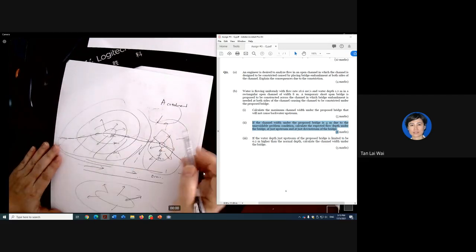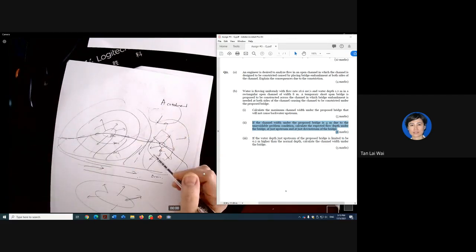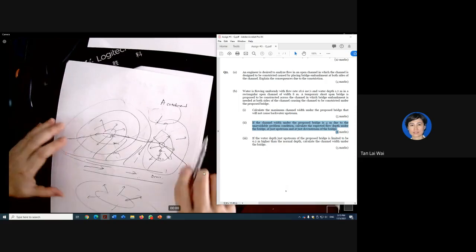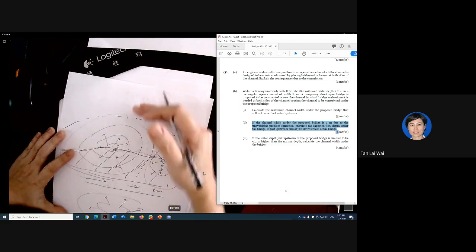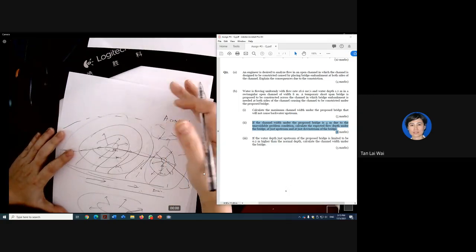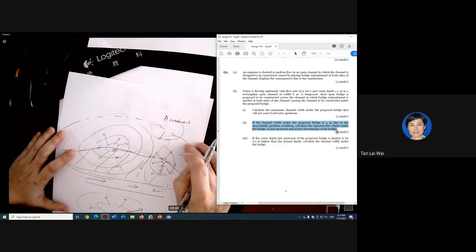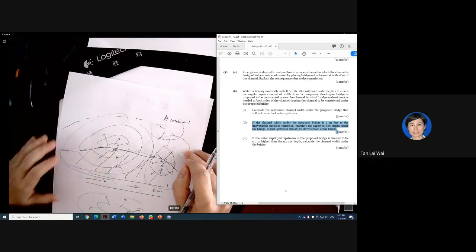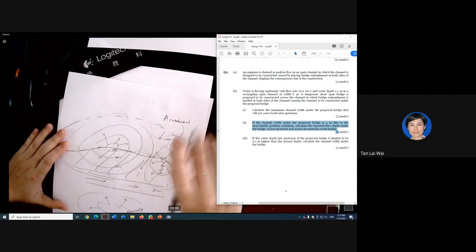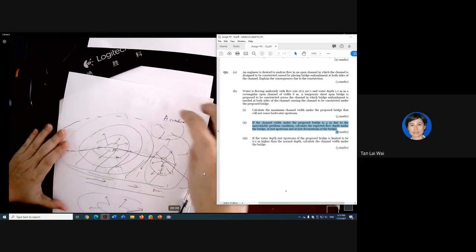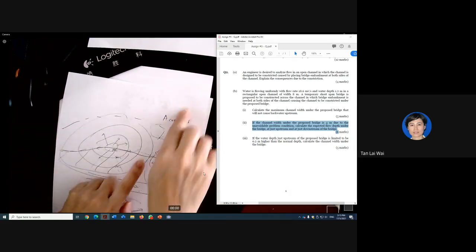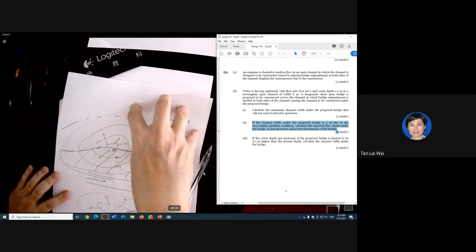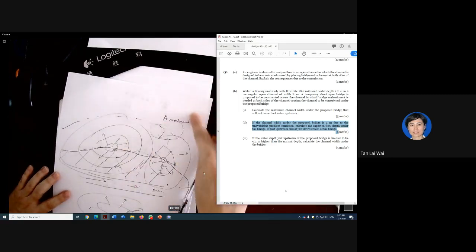Sometimes in our survey plan, they only give you up to a certain boundary. You don't know what happened further upstream. Therefore, what you need to do is go on site to survey what are the areas here. If there's a pond, then you are safe because you know that the water could be draining there. But if this is higher ground, then you need to cater some more.